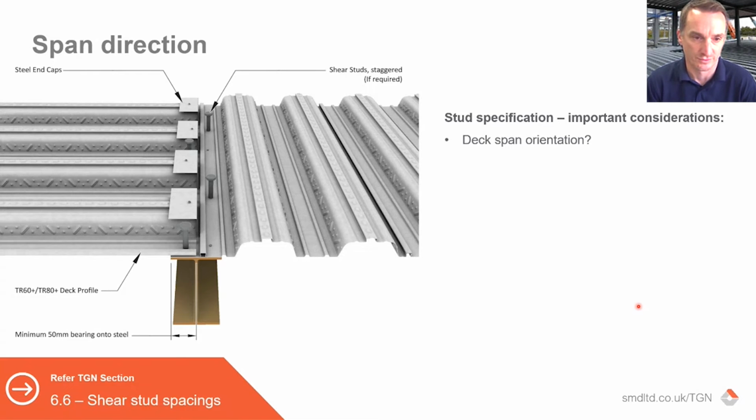So perhaps on that beam, by looking at it in a specific scenario, you could actually design it with closer than 333 centers, depending on how big the beam center is, the beam width is, sorry, and where you can put those studs on that right-hand side.